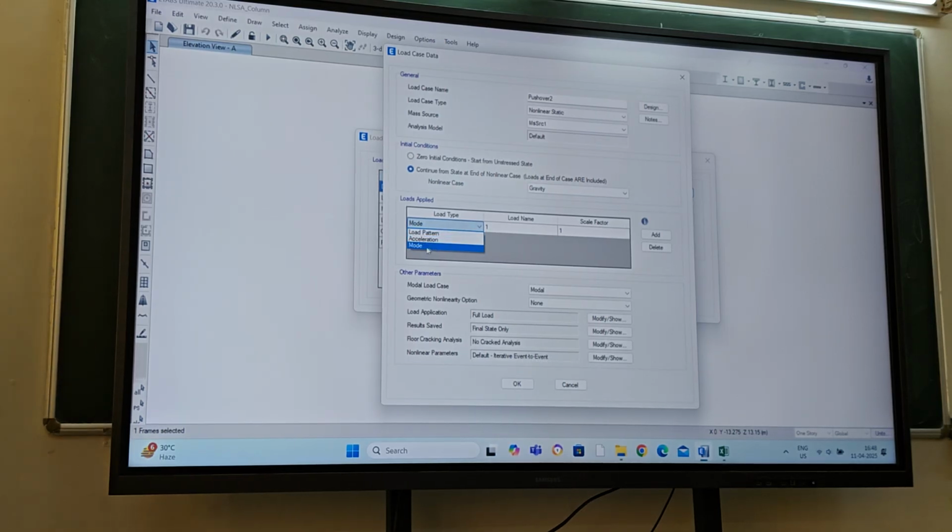But it is easy, and mostly the option selected here is mode shape, meaning you go according to your mode shape. Which mode? Based on modal analysis, you identify which is the first mode for your direction, and accordingly you choose it. I'll check this from the modal analysis and we come back here once again. In scale vector you can leave it. Then choose the model here, and choose the behavior locally.